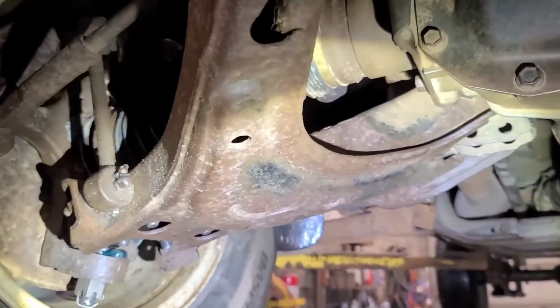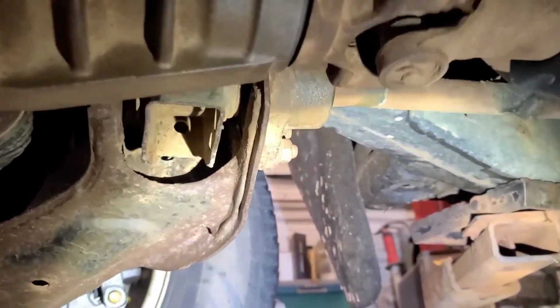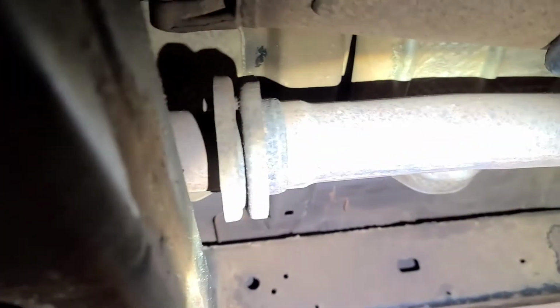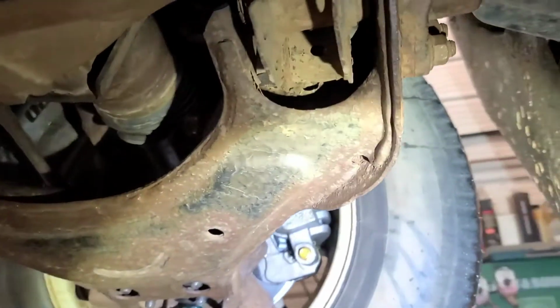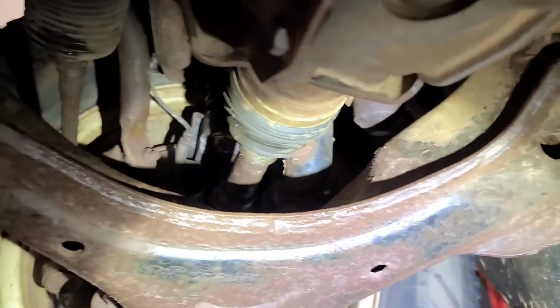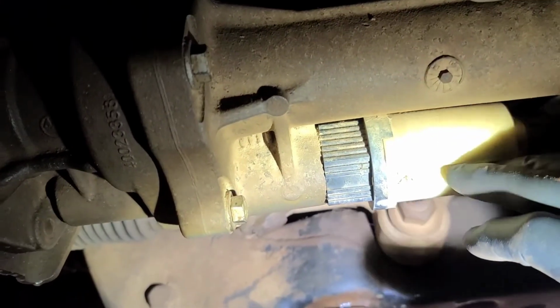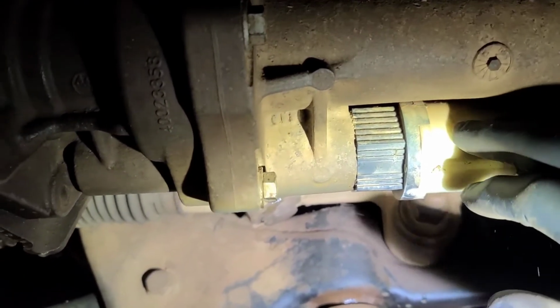Okay, so right now, transfer case is in two-wheel drive. Front axle is not connected. Turn the front drive shaft. I got the main transmission in neutral, so I can turn the drive shaft. So I'm going to have an assistant put it into four-wheel drive high. I have an assistant in the truck, and we're going to listen. I got to wait for the compressor to shut off. Okay, so this is the front axle connect motor, and right now it is not connected.